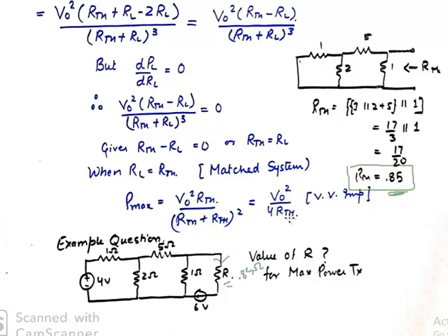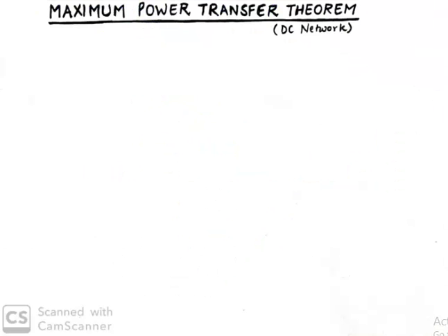So this theorem is super important from the point of view of examinations and competitive examinations. Many a times you will be asked to find the maximum power delivered at the load, so you need to find RTH and VTH both and then calculate the maximum power delivered. So I hope this quick introduction tutorial to the derivation of maximum power transfer theorem was of help.